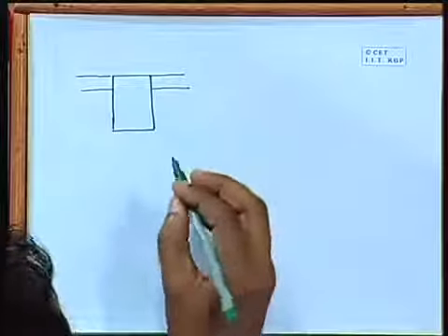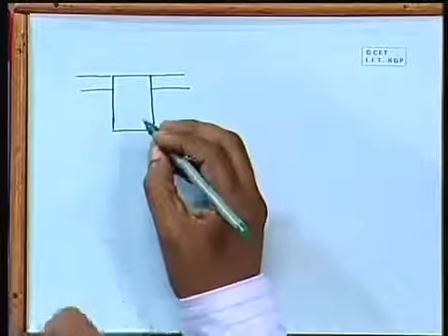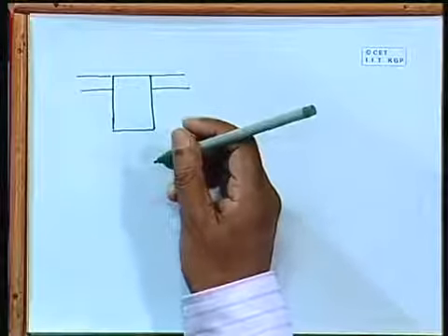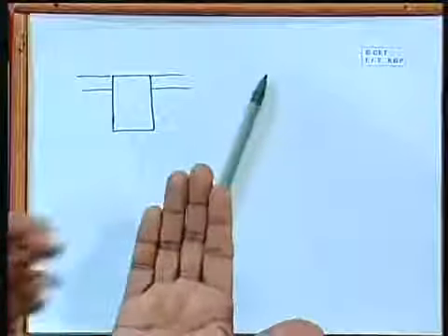Okay. We have to provide the reinforcement, because concrete is very weak in tension. Concrete can take compression. That means if you press it, it can take enormous load. But if you pull it or bend it so that tension develops, its capacity is very, very low. Almost we ignore it, we neglect it. That means concrete does not take tension.